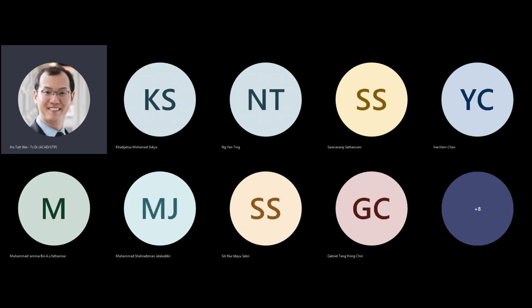It's called a semiconductor because there are almost no free carriers there, right? And you want to contrast this to a metal. When you talk about metal, you basically have a lot of free electrons floating around, so that if you were to attach this portion here to a positive voltage and here to ground, these free electrons will be swept and they will move by what we know as drift current.